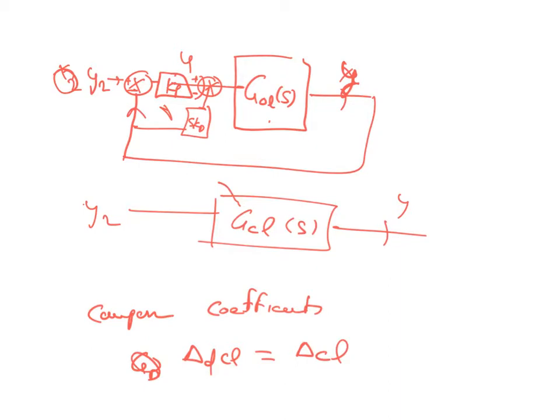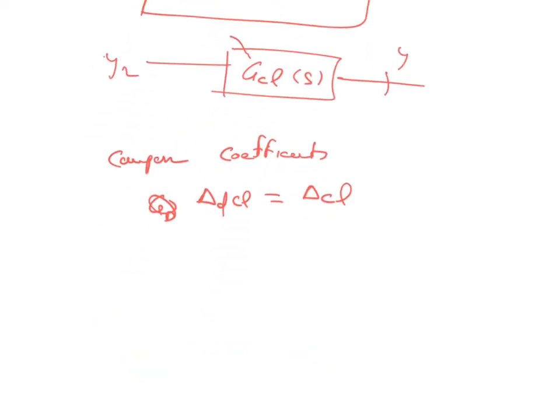At least that will be the starting point of your gains, so that if everything is ideal, these gains should work. Then once you see my response, you can go back and tune them. Here they might not be necessary because it's a simple system, but when we move on to the UAV, you might need tuning as well.